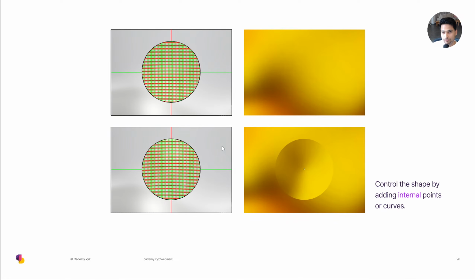Okay, so if you look at the top example, we have a surface where we cut out a hole and I patched it using the patch command, and you see the EMAP effect of that, like a shiny effect of that surface. And you can see it works amazingly to cover up that hole. But in the bottom case, I did the same operation, but this time I added a point as well as the input. And using the point, I could create this dimple effect.